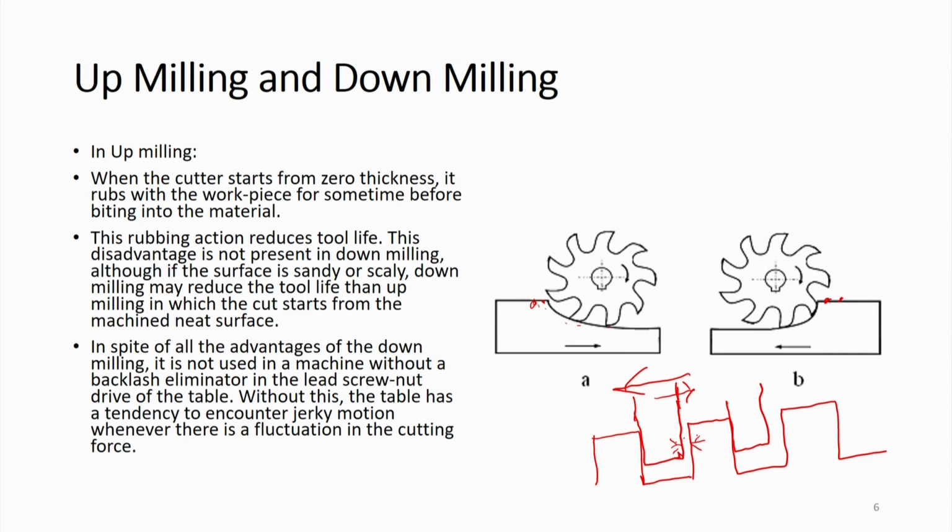So, for backlash elimination sometimes people use a double nut compensation arrangement. Suppose you have this type of screw with many teeth, I am not showing them all, and I put one nut in which the teeth are aligned in this direction.